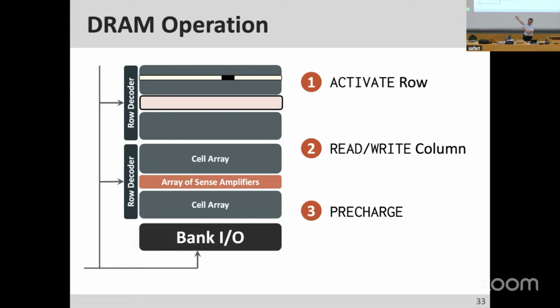Now, basically, there needs to be some circuit that I didn't explain to do that, but this is the pre-charge circuitry. Essentially, pre-charge circuitry changes the voltages such that first it writes back the data into the cells, which actually happens kind of automatically, but then sets the voltages of the sense amplifier to 1/2 VDD on either side so that you can start the next access reliably. That's the pre-charge operation. Basically, the row becomes closed after that so that you can activate another row so that you can sense that row reliably.